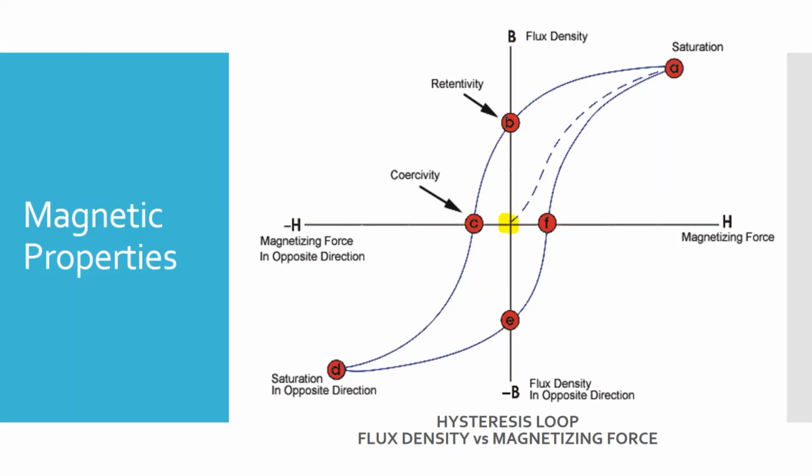And when we first turn on a current, they're going to follow that dashed line. And what'll happen is they'll follow the dashed line, and you can see the strength of the magnetic field goes up, and then it continues to go up, but slower and slower and slower till it reaches something called the saturation point.